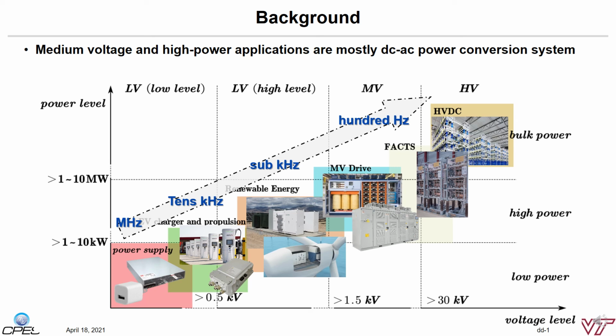High-frequency power electronics dominates the applications in the low-voltage space, including switching mode power supplies for electronics, telecoms, and information technology industries. The power rating of these low-voltage applications is a few watts to a few kilowatts. Recently, there are many emerging applications like EV charging systems, traction drives, and energy storage, with the voltage ranging from a few hundred volts to over 1 kilovolt, and the power ratings can reach a few hundred kilowatts.